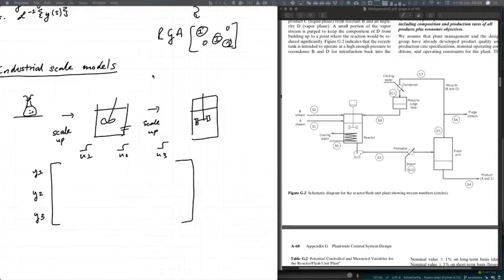And they'll say, oh, okay, well, U1 has no effect on Y1. But it has kind of maybe like a first order effect on Y2, and maybe that gain is 2, and it has a negative kind of effect on Y3, and maybe that gain is -10, right? And so by filling in this matrix in this kind of order of magnitude way, you're doing intelligent guessing.